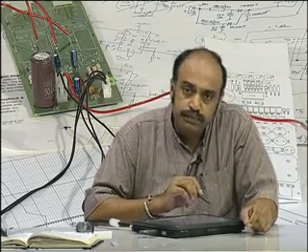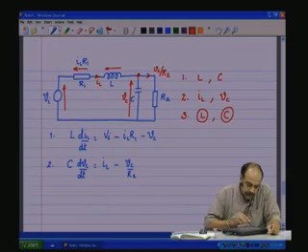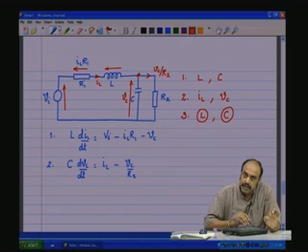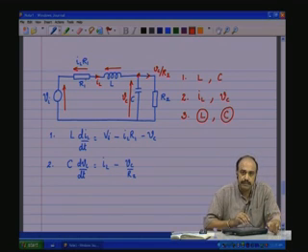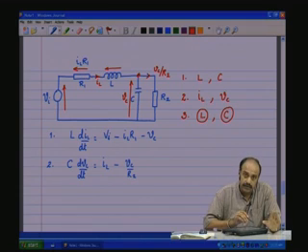And if it is a loop, like we see here, just check if all the voltages across the components have been identified. Like for example, in the case of the resistance here, it was not identified, but it will always be expressible in terms of a state variable.